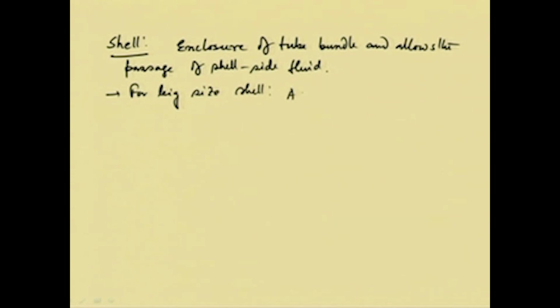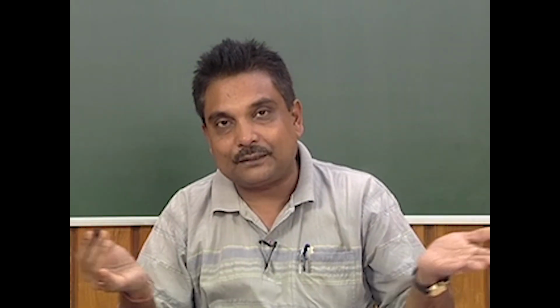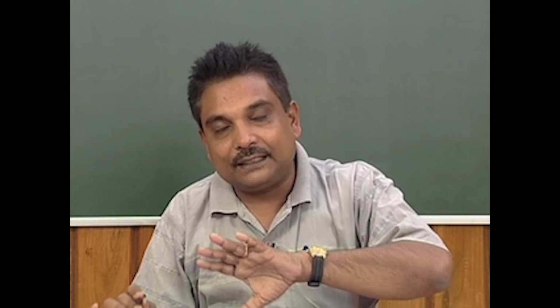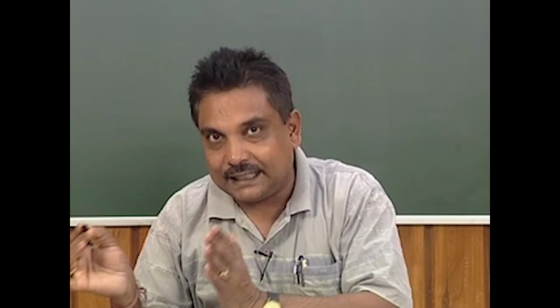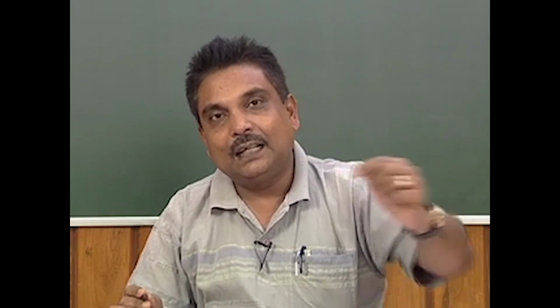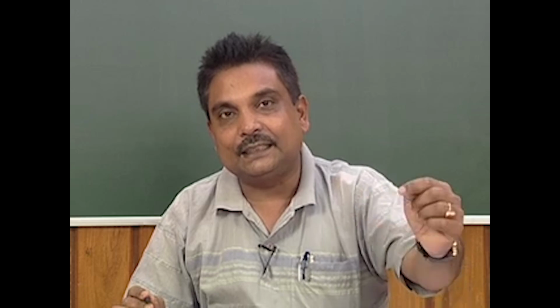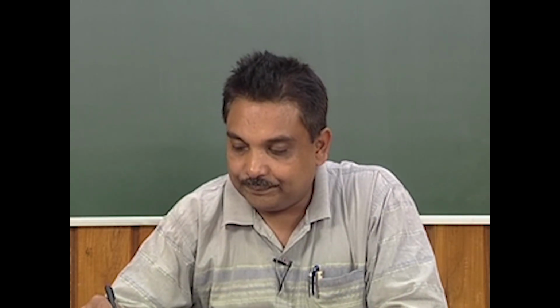The plate is under heat treatment, so it is hot, and then it is rolled to a diameter of the specific size we require, and then in the longitudinal or axial direction it is welded.